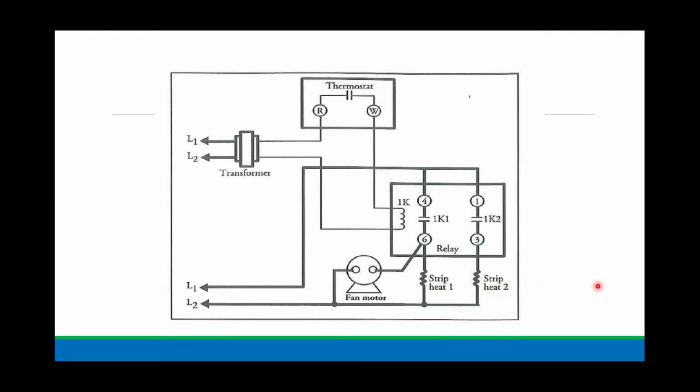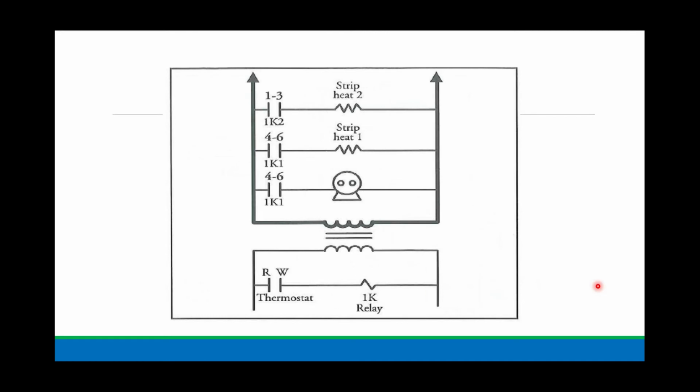Now here's the same diagram in a ladder diagram. And I love ladder diagrams because ladder diagrams to me are much clearer, and you could see the sequence of operation clearer. And why do we call it a ladder diagram? Because, gentlemen, these are rungs. So across each rung, I can have as many switches as I need, and if there's going to be multiple loads, they could be there too. Again, dark drawn lines with arrowheads are line voltage, lightly drawn lines are low voltage. In between, the transformer. So how do we energize this system? No different than what you just saw.